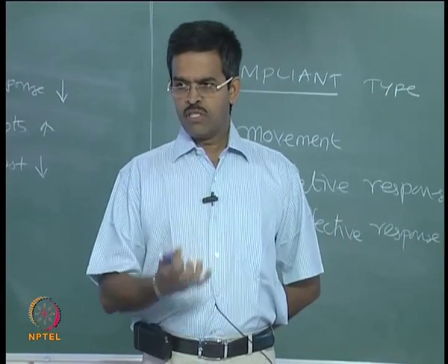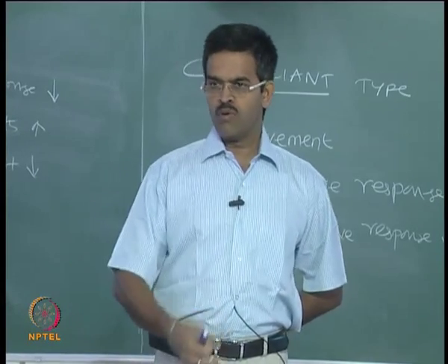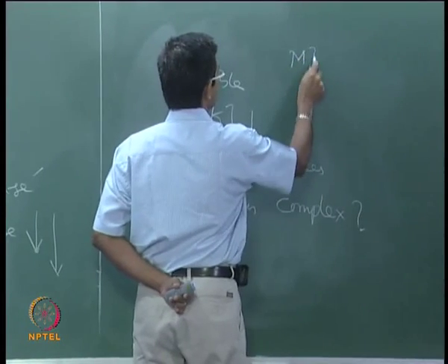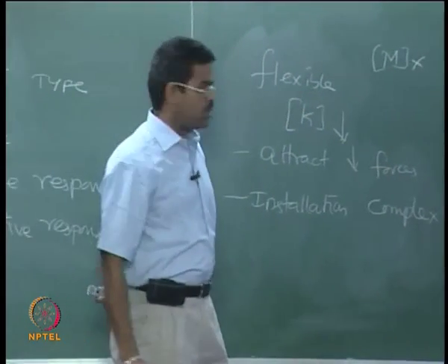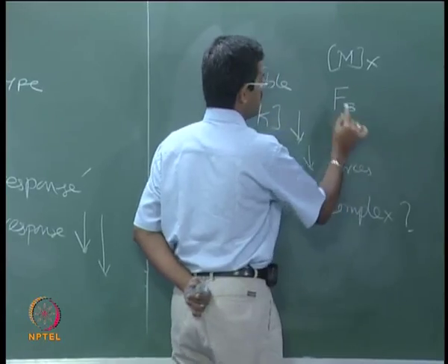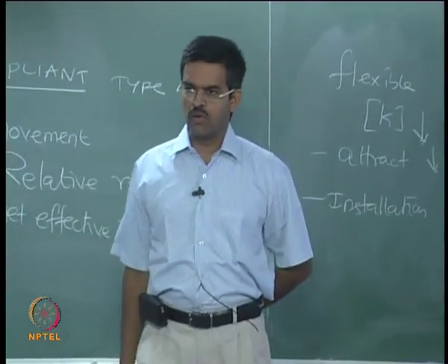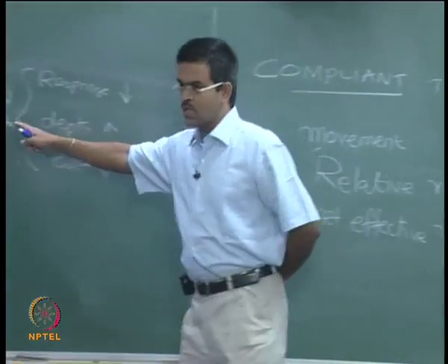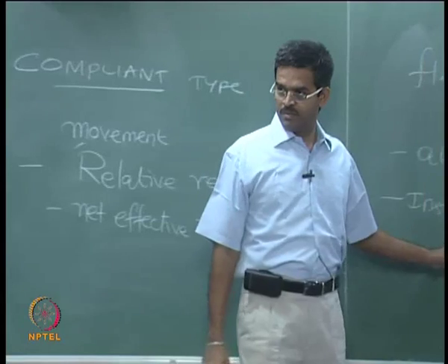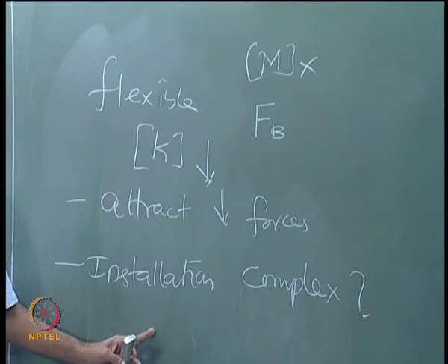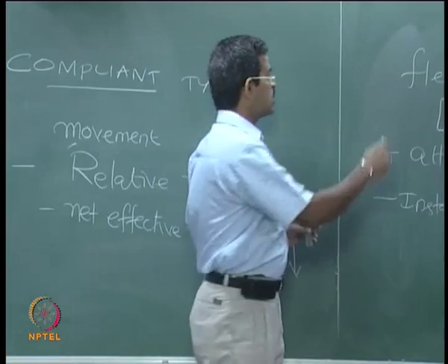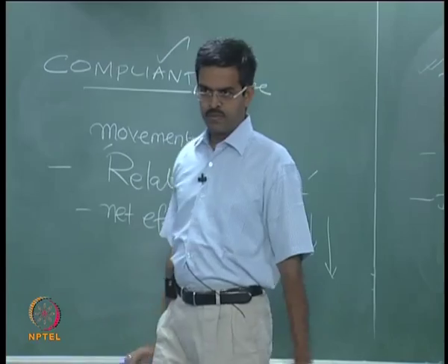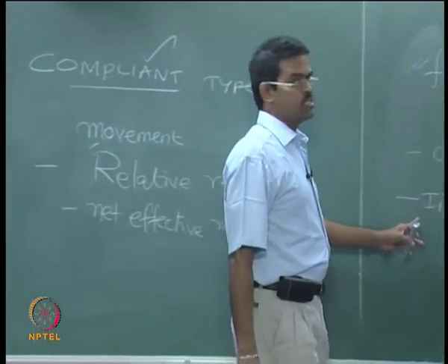The position fixity of the body in a large volume of water does not depend only on mass, but also depends on the buoyancy force which the fluid will exert on this body. Whereas in the earlier fixed type form we did not have this problem during installation, in compliant type, because of the flexibility introduced in the form, you have complexities in installation.